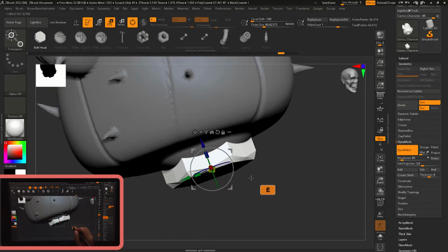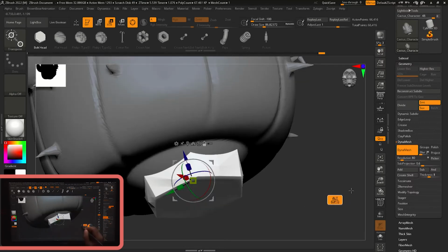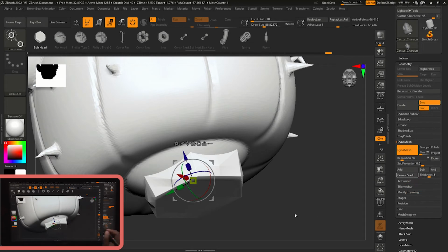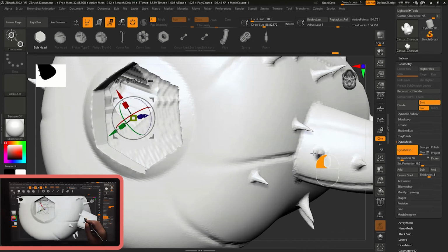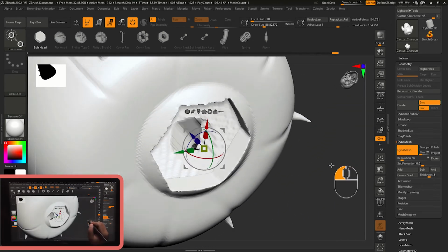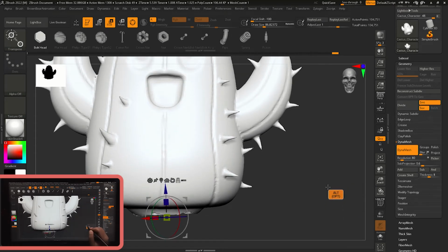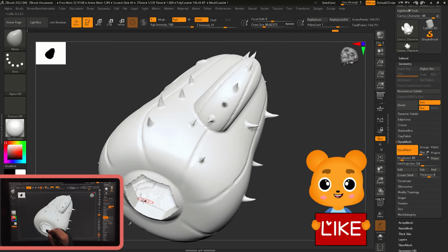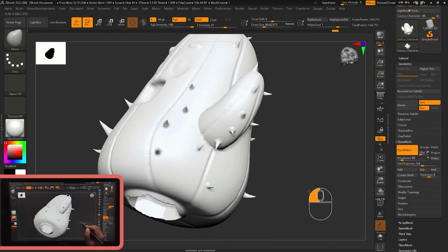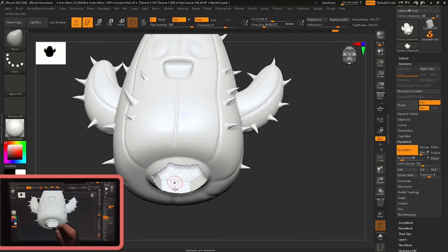Let's see if I can show you better by just inserting this mesh onto this mesh and removing the mask and just Create Shell, and you will see the hollowness inside. You can see the hollow model inside. So this option is very helpful when you want to create a 3D print, so that the extra amount of residue, the resin or the filament, will not get trapped inside it. So the Create Shell option was there, and the Thickness controls the amount of thickness which we have here.